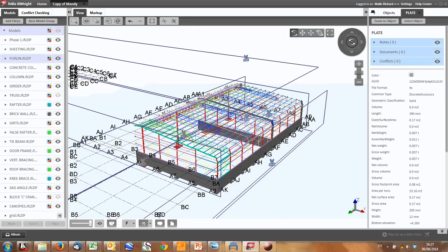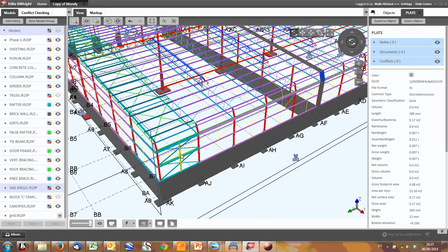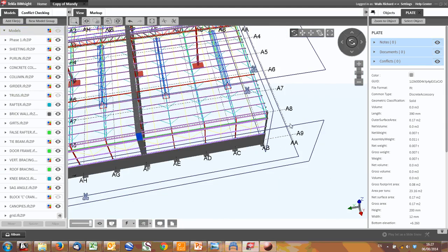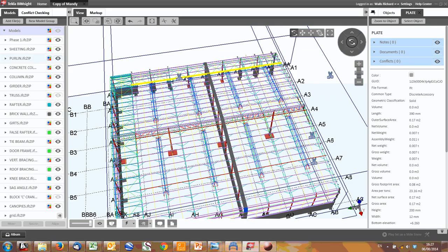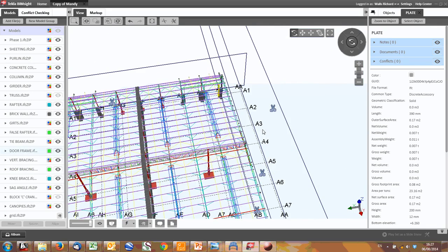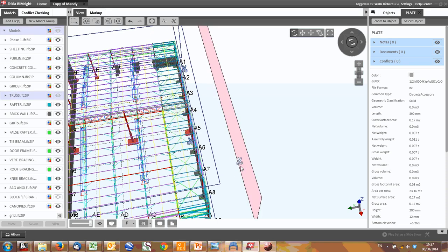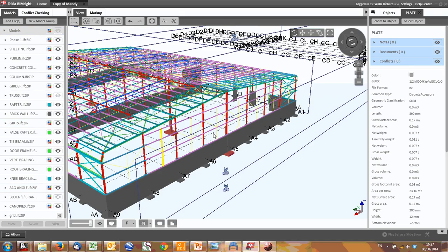And on the outside of the building, let's take the sections back. We've got bracing down the side. This is vertical bracing. This is horizontal roof bracing. Same this side. And vertical roof bracing there. And we've got some more bracing in this outer bay. There we go. Roof bracing, vertical bracing. And as you see, the gable columns.